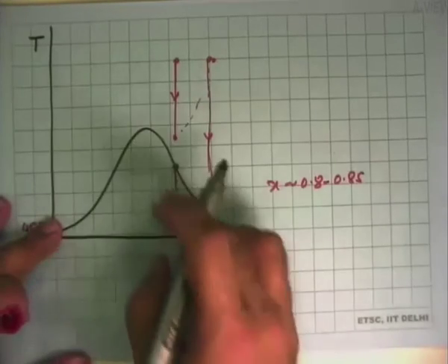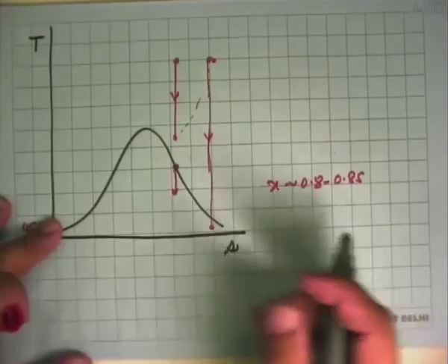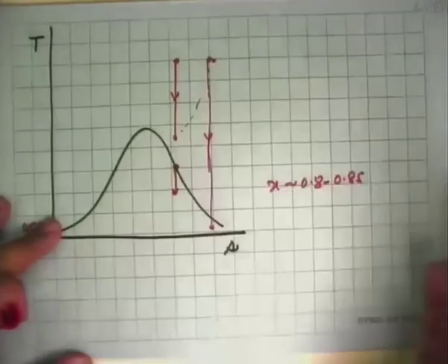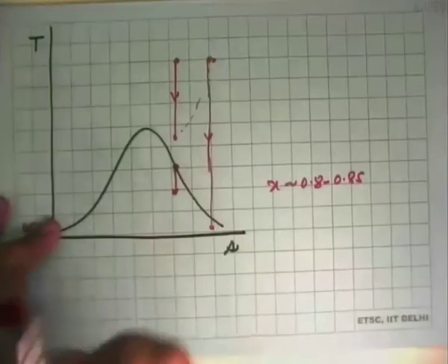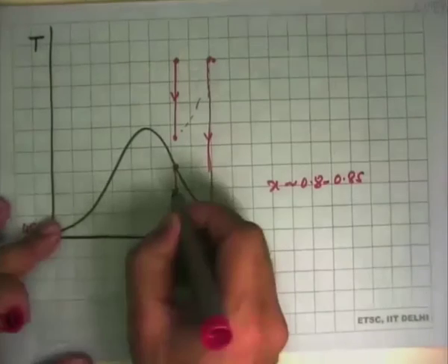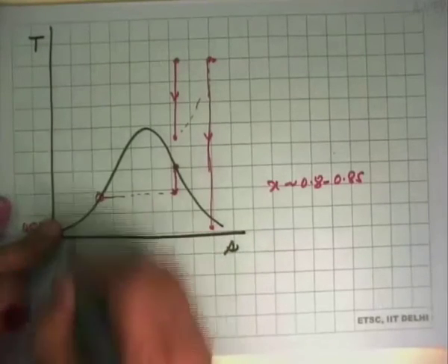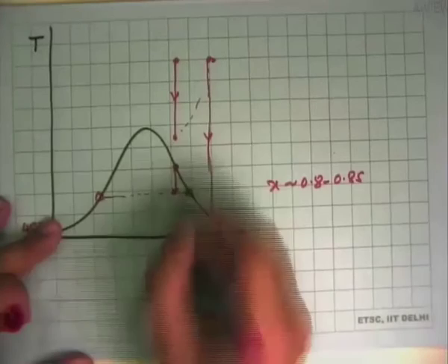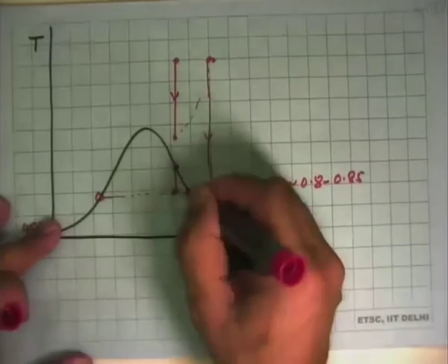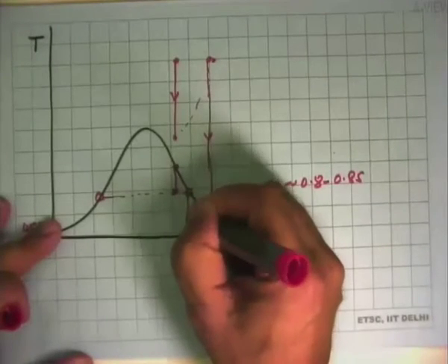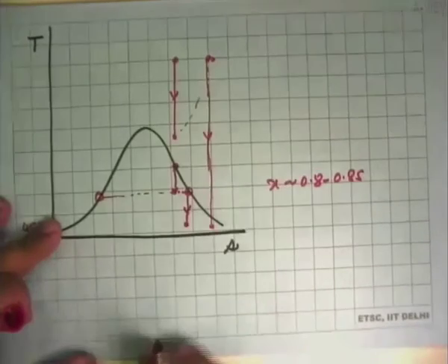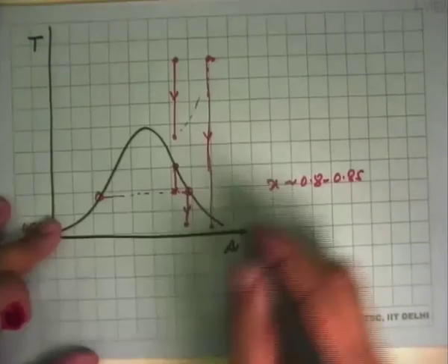So what we will do is take this steam out and physically separate the liquid from the vapor, because there is a big density difference. The vapor state, when it is separated from here, will come over here, and the liquid state from here will go over there. Then we put it into another turbine and expand it until the cooling temperature is reached. So this is a physical separation device.